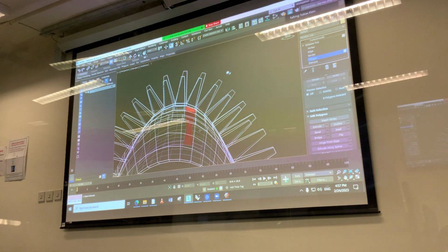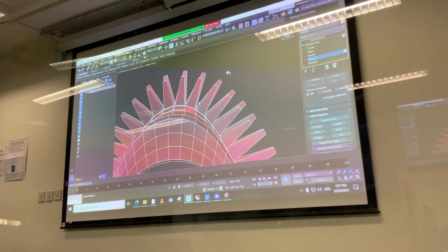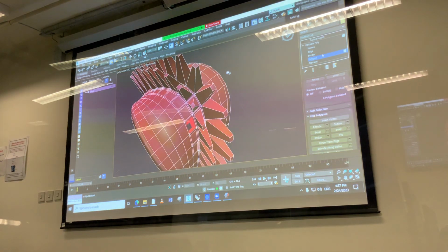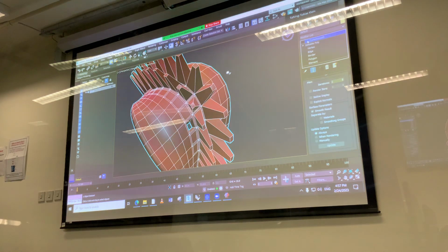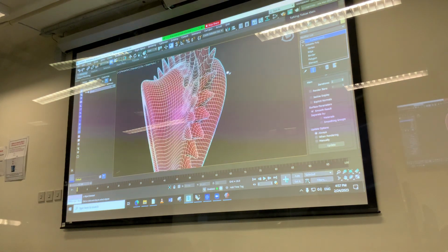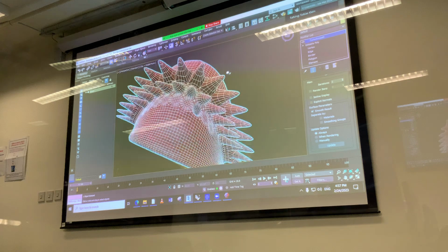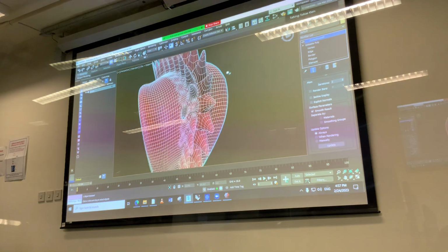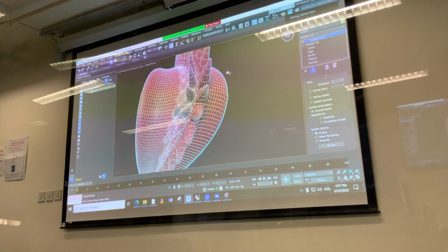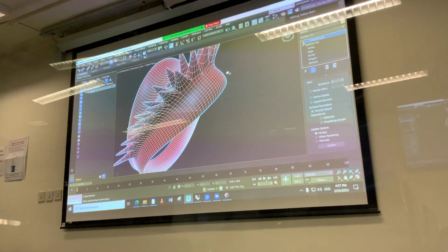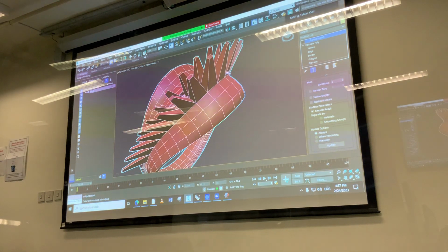Say yes. Now if we go back to our shaded, our clay modeling, and we switch the polygon off, go back to the turbo smooth, switch it on. Now we basically get a ring. So we have spikes as expression outwards, and we got holes already going inwards. So that's pretty neat. We can obviously combine them.